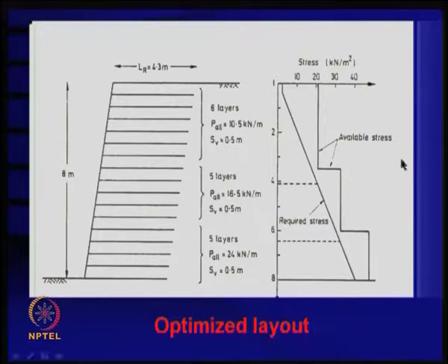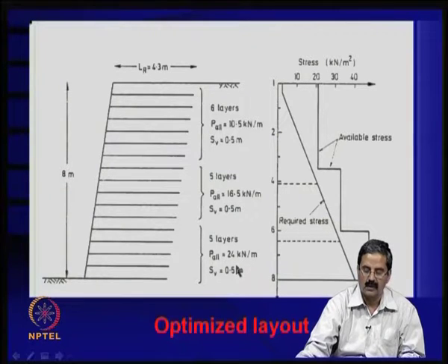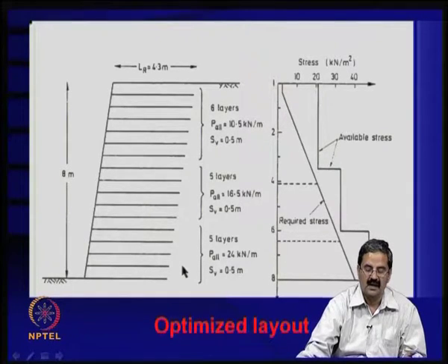So, the way that we calculated the design also directly had the factors of safety, because we got these numbers based on time and other extrapolation numbers, damage effects and all that. Those numbers were considerably reduced and we got the design. So, this is the length of the reinforcement required, this is the spacing required, and this is the type of geogrid required. This is what the answer is. If I want to say that this is the suitable reinforcement configuration, yes, this is that.